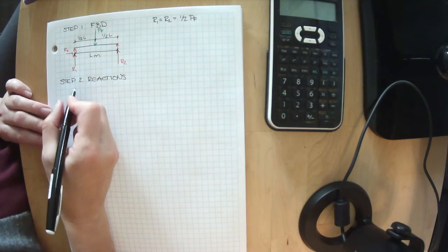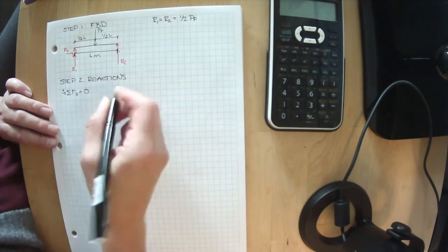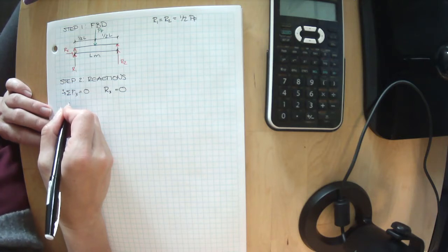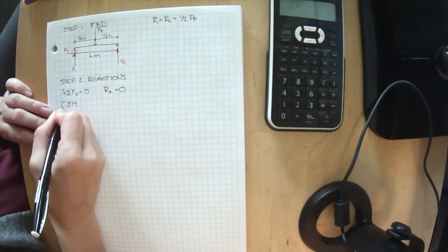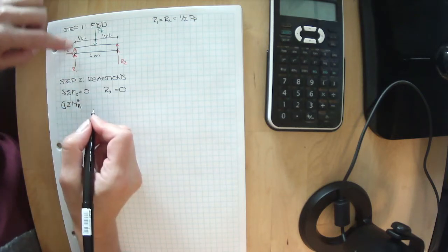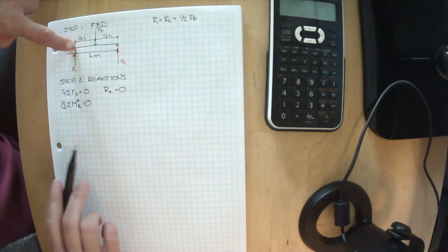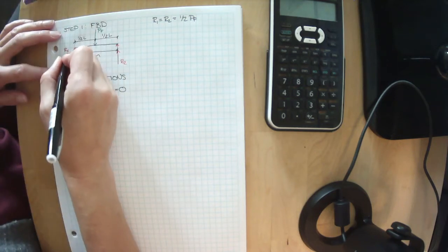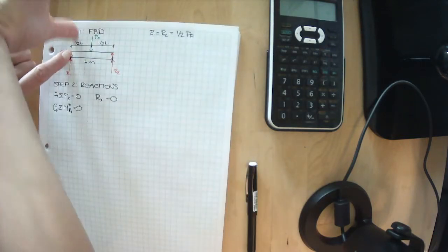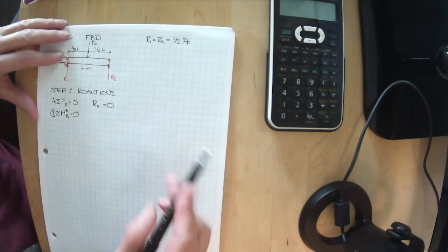All right, we know that we can sum all the forces in the x direction. So Rx equals 0. Let's sum the moments with everything spinning in that direction being positive, about the z-axis, and I'm going to pick R1. I'm going to put my thumbtack right here. If I'm putting my thumbtack right here, R1 passes through it, Rx passes through it. PF is spinning it in that direction. So we curl our right hand fingers, and we see that PF is spinning it in the negative direction.